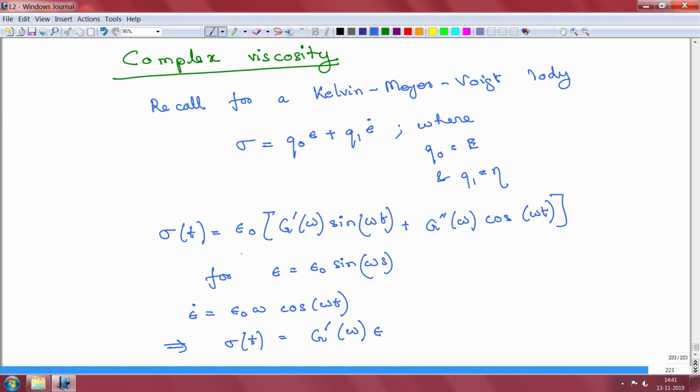Okay. So, this first part is epsilon and this second part is epsilon dot, so I have recast that equation. This is the generic response, right, and I have recast this for the case of the Kelvin-Voigt body equation. Okay. So, this is the governing equation for this, and using the general response I have been able to rewrite it in this particular form, because epsilon naught sin omega t is epsilon of t and this other one is related to epsilon dot.